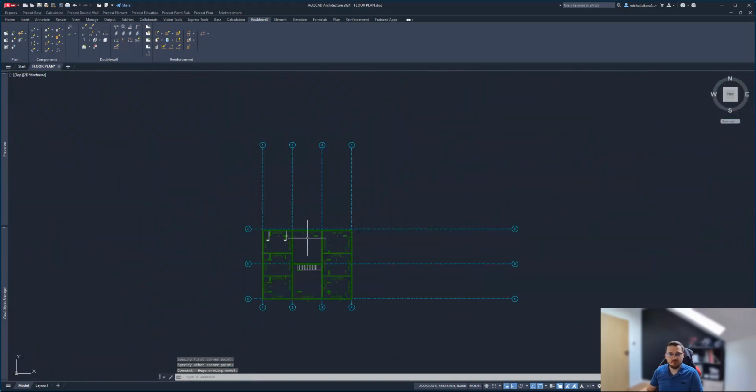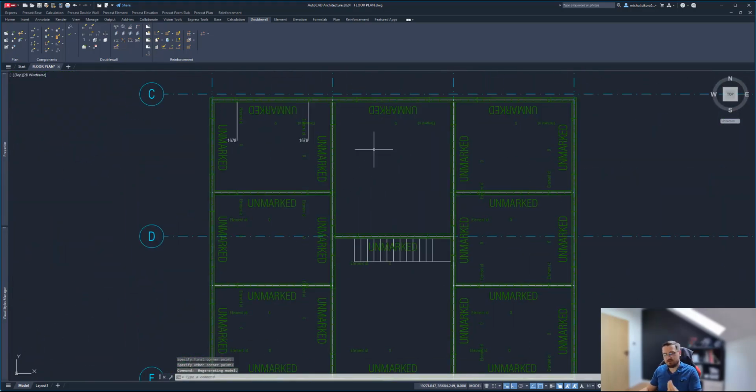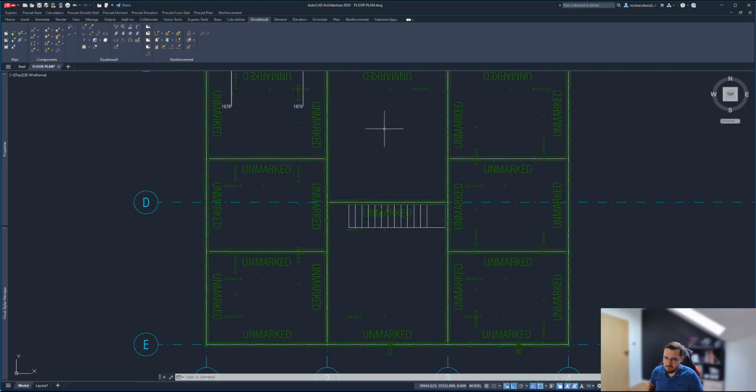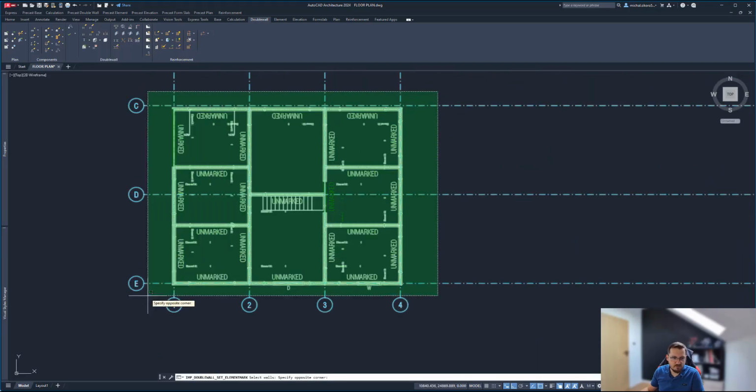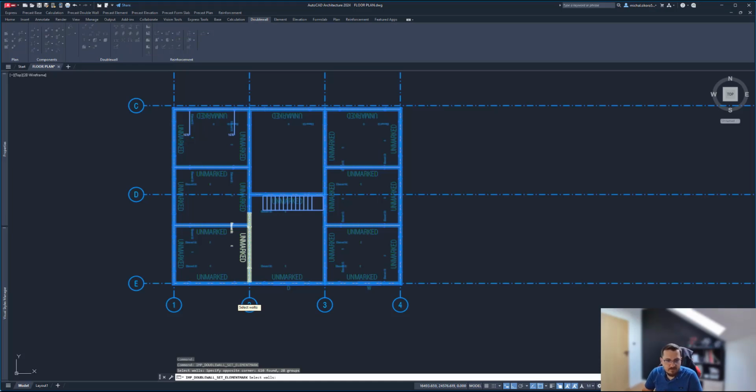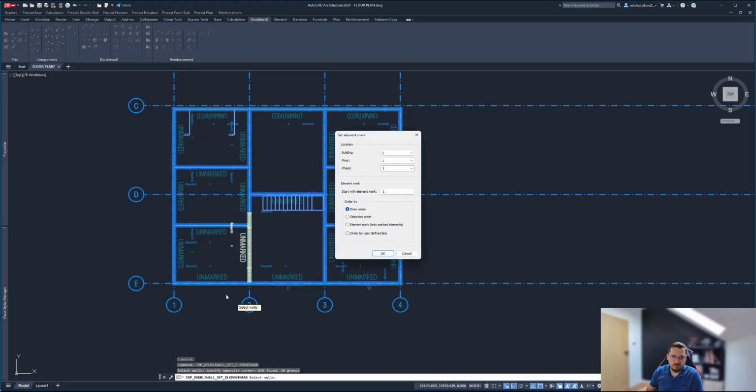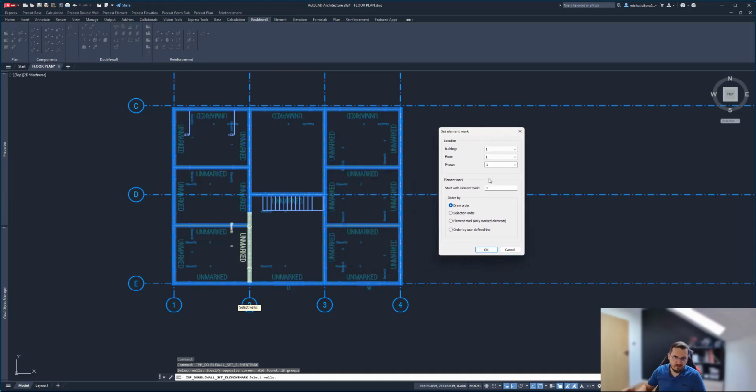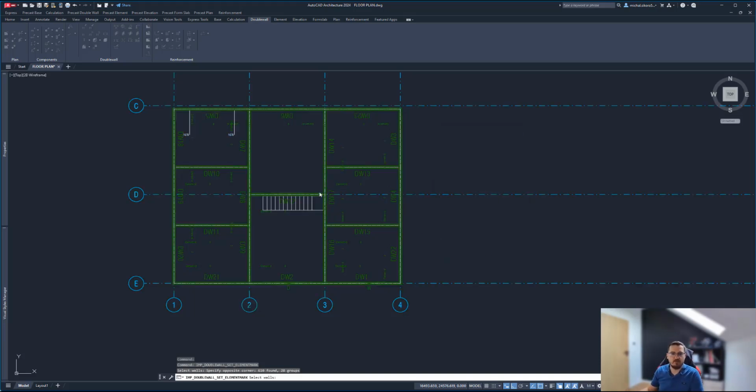So how do you now get drawings out of it or save it? Because all the elements are unmarked. The process is a bit different than with other elements in Impact. We have to set the marks manually for our elements. So I'm going to select the walls. That works for double walls. With that, the double walls will be saved with a prefix that we have set in the element settings. I start with the element mark. It can be 1, draw order or selection order. That basically determines what numbering order is placed upon the elements. And as you can see, we have different wall types.